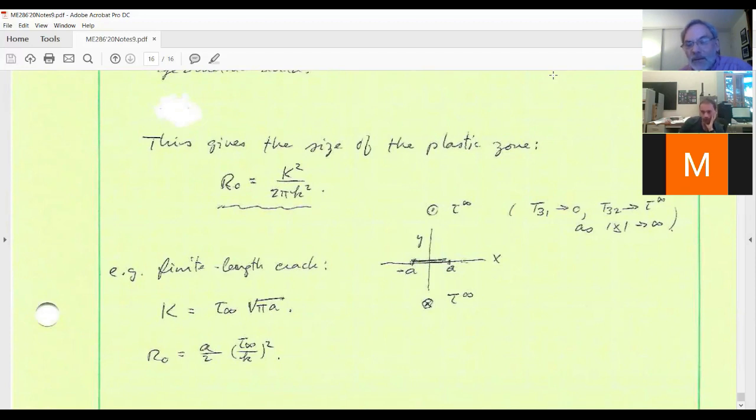No. Here, this plastic zone, the circular plastic zone, is peculiar to anti-plane shear. In mode 1, for example, you'll have something similar to what we had before. In the rigid perfectly plastic case, we called it the Prandtl solution, where we had centered fans and so on, but it's modified by the presence of elasticity.